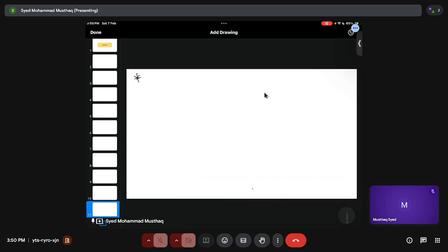So what does sieving have, right? Sieving is nothing but passing your powder particles through some holes, or a better way of saying it, an aperture. So you pass powder particles through an aperture. Now there are some standards we follow. Each sieve will have a certain number. There are different types of standards, and each company will follow one. There are only a few standards, not a very large amount, because people get confused. The companies mostly follow one or two standards. That's all. So they give a number.